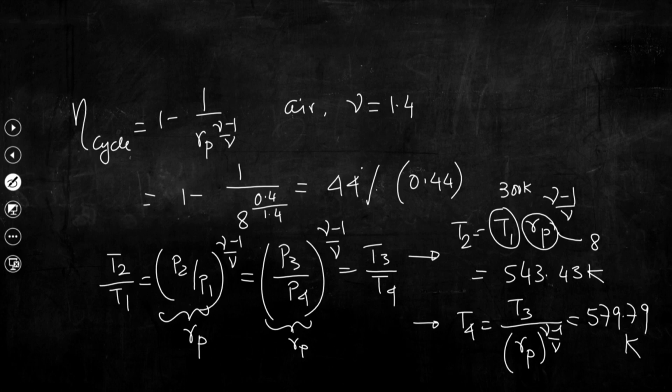You can understand that the rise in temperature of the working fluid at the end of the compression is even less than the temperature of the exhaust gas. So, a substantial amount of energy is getting lost, because T4 is even higher than T2.